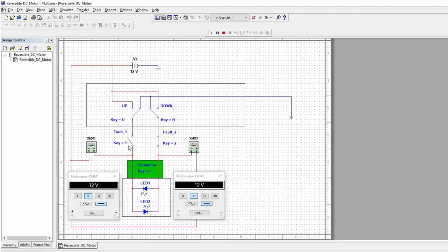So what's happening is this current is backfeeding through the motor and it's going up through this line. And that's what you have to remember. When you are checking this circuitry, have a look and make sure that this electricity can only be following the path you want it to follow, the path you want to check.